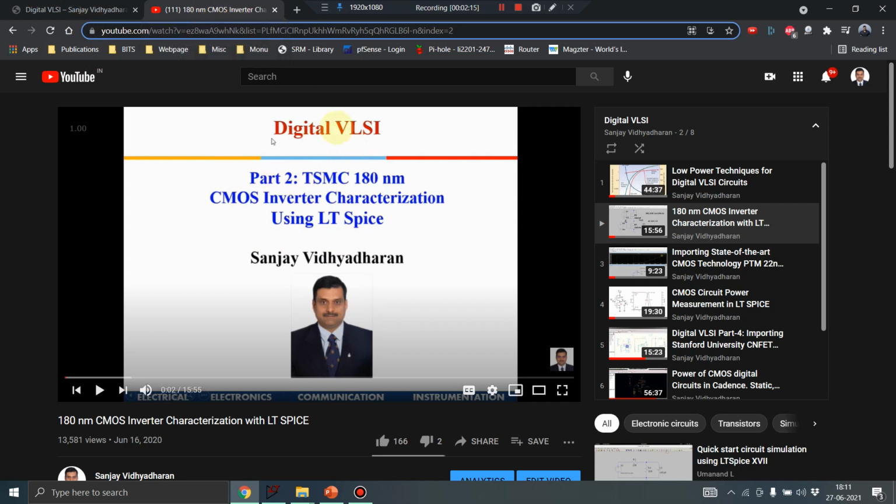channel, okay, and then you have a playlist known as Digital VLSI. In that you have a particular video, the second video in that playlist, which is titled TSMC 180 nanometer CMOS inverter characterization using LTSpice. Here I have explained how to import the TSMC 180 nanometer technology library into LTSpice. So you need to do that first to proceed and try to characterize the NMOS. So first you need to do that.